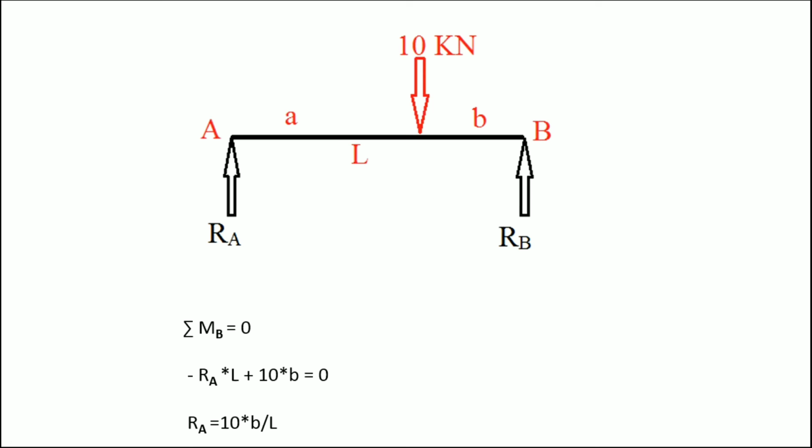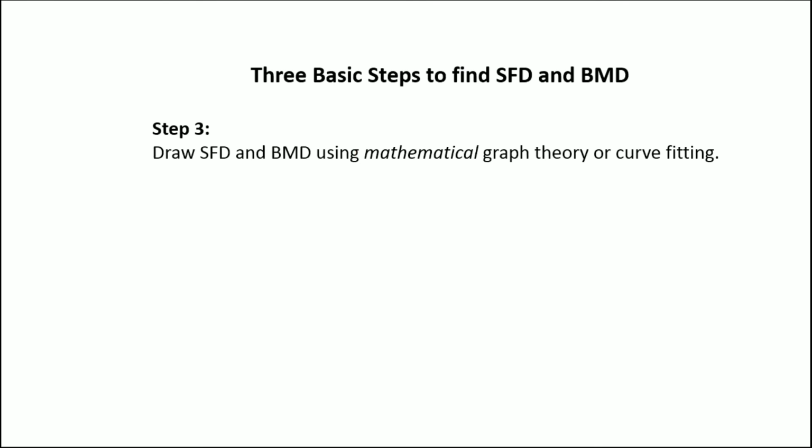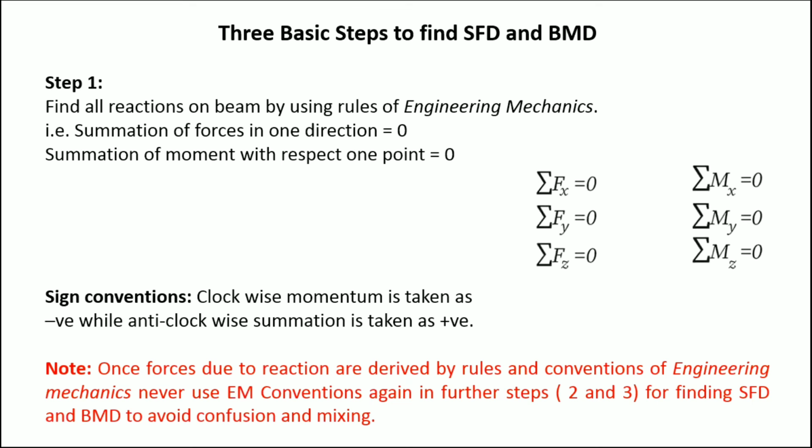This is only about finding the reaction forces. Do not confuse it with shear forces. We will discuss the shear force diagram, finding shear forces and BMD in the next lecture. Just look at the 3 steps only. The first step we have discussed. In this, we have taken clockwise moment negative and anti-clockwise moment positive. This is all about finding the reaction forces.